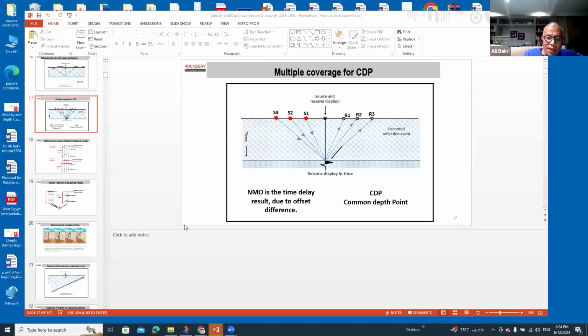So I have the time to the top and the time to the bottom. Let me use this also. In front of you, this is the top of my layer, and this is the base of my layer. So I know the thickness of the layer from the well. Say it's 100 meters. But I'd like to test how I can calculate the thickness of my layer. I know it's 100, but I'd like to test it. So I have the time from here to here, which is two-way time. I divide it by 2 to get the one-way time, and then I multiply this one-way time by the velocity that I measured at that well. I can come up with the thickness. I'm going to compare the thickness that I got from here with the thickness of the well to make sure that it's the same thickness. Very simple.